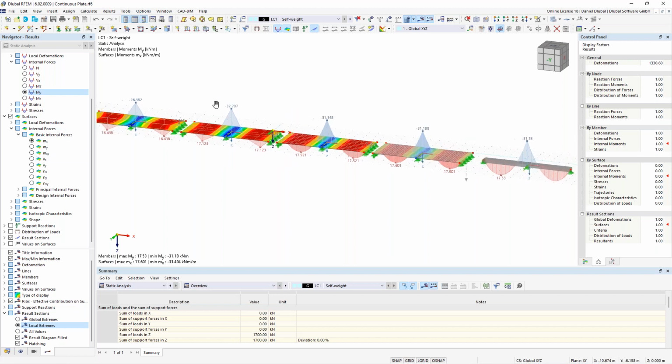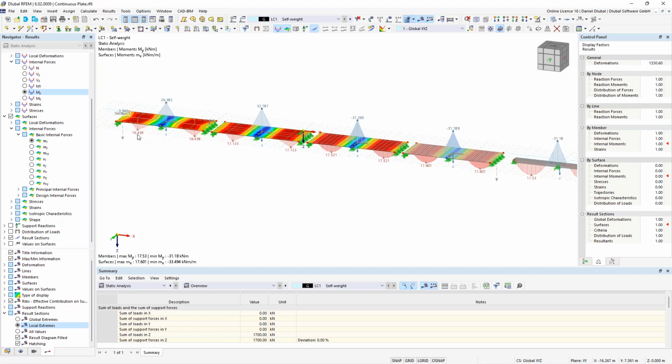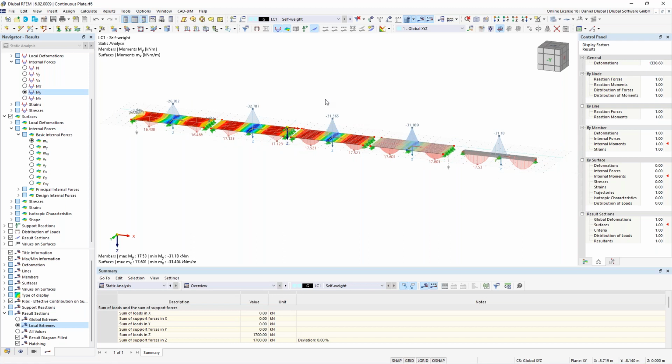So also here at the field moments, 16, 17, and here we have 70, 53. So this is also a difference. In order to summarize it, it is important for FE calculations that you choose the FE mesh as fine as necessary and as rough as possible. Here on the left side, we have it too rough, so we underestimate the results in comparison to our beam example.